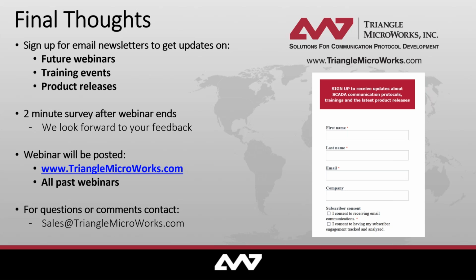So you can also use it to go from an IED and be subscribed by, like, a gateway or an HMI. But keep in mind that when you use Goose for that purpose, first of all, it's published to everybody at the same time. And if your HMI is offline or you have lost the communication, you will not be able to later on get the events. That's why we typically have reporting with buffered reports, so the events will be buffered and you can get them later on, so you can establish your sequence of events.